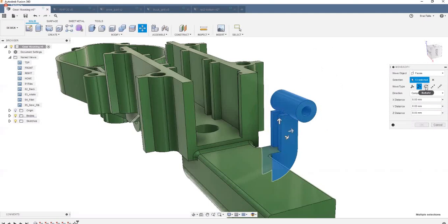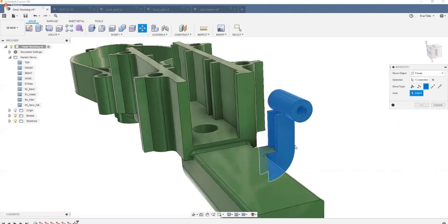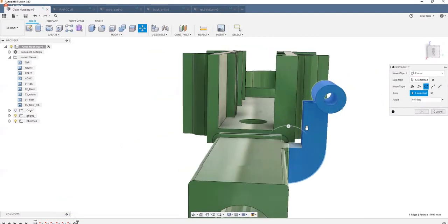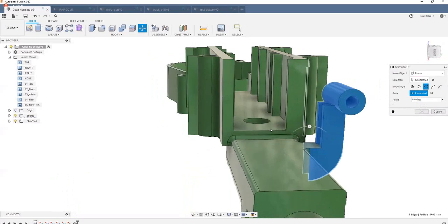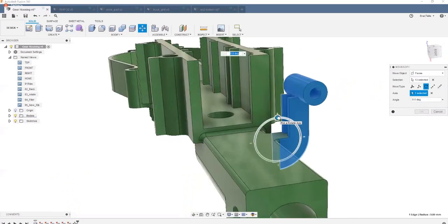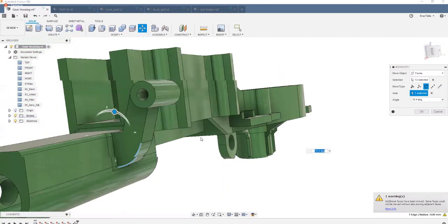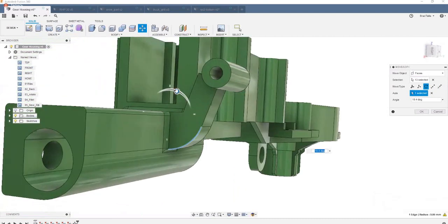Okay. I'm also going to say rotate. And let's just go ahead and click on either a round face or a round edge. It doesn't really matter. This is my favorite part. Check this out. I can grab, let me move over just a little bit, grab this guy and start to rotate, and you'll see a live preview of what that's going to look like. So it's actually rotating those faces around this edge.